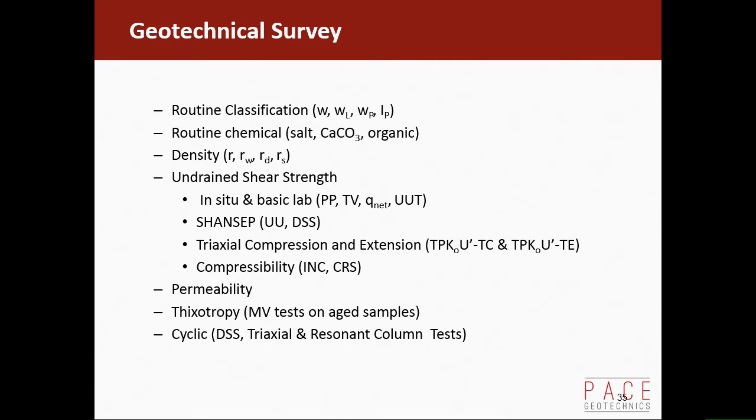And you know, the routine stuff, the soils have slightly different strengths in extension, direct shear, and compression in triaxial, so we allow for that. And thixotropy is to do with the recovery of strength with time. So, what I've talked about, understanding how that works is an important part of the design process. And we also did some cyclic tests as well to understand how the strength of the clay changed with the number of load cycles that it experienced.